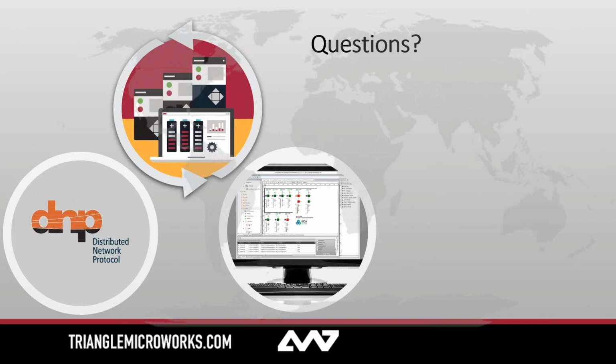Okay. If there are communication problems between IEDs and the master, is it possible to determine the error? Yeah, so one section I didn't really highlight in this webinar, at the very bottom, is an output, and you can configure what shows up in this output, but any sort of communication errors is going to be popped out down there. So if you connect and then it's immediately rejected because you lost connection, say someone ripped an Ethernet cable out of your computer, or you lost wireless or whatever you're doing, you'll see the failure right there down in the output.